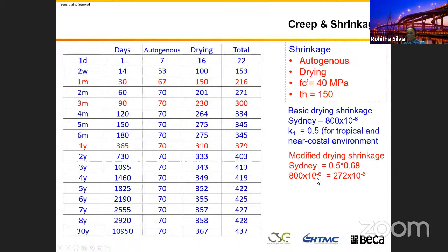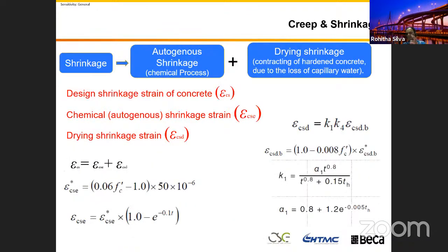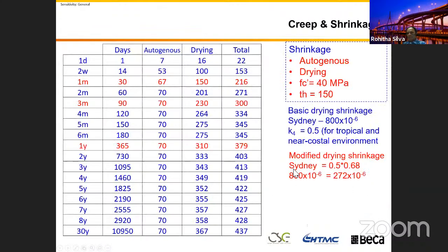When calculating shrinkage and creep, we need to have a base, and that's what they started with. Then I put in the times: day 1, 14 days later, 1 month later, 3 months later, 1 year later, 30 years later.